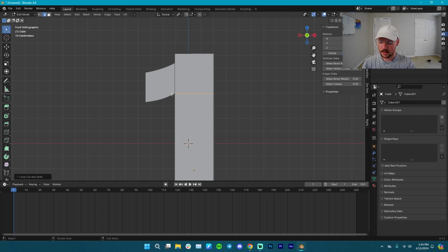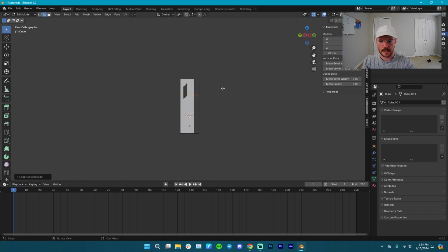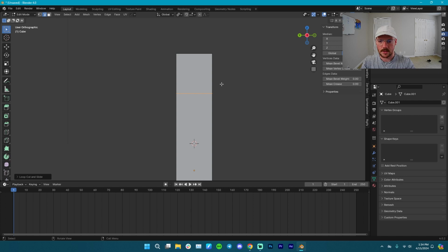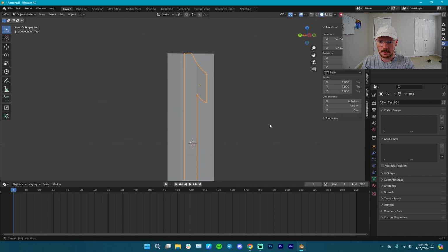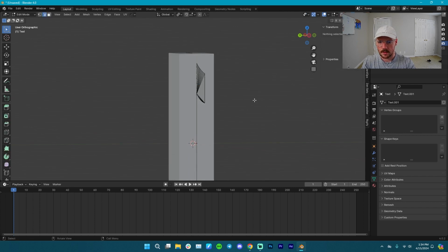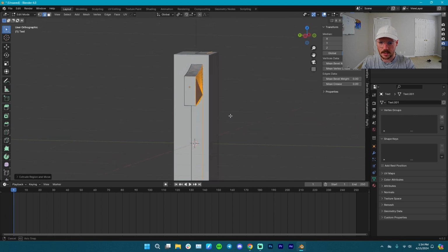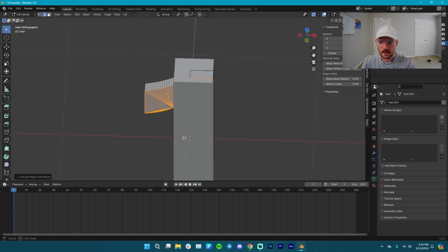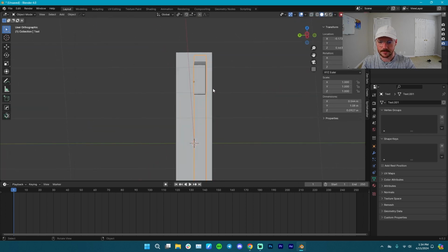And then I'm going to hold Alt down, and I'm going to click and hold middle mouse again and drag. And now we're looking at it from an angle. So we're looking at it from this angle, right? So now what I can do is tab out of this. I'm going to actually extrude this a little bit just so I can see what I'm doing here. So I'm going to go tab for edit mode, all, extrude. Should already be on the Z axis. That's fine. Tab. And now I can just see what I'm doing.